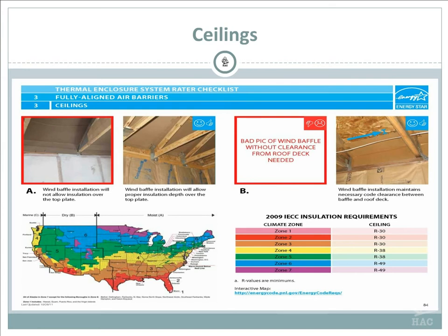Again, these are only over the vents. If you have a continuous vent, then yeah, you're going to be doing every one. But if you just have soffit vents with a high-low ventilation, you could probably get by with maybe 10 of these, again depending on your area. So that's your zones for insulation and your climate zone. Again, these are all in the books that we gave you, and it gives you the little page number on the side there.